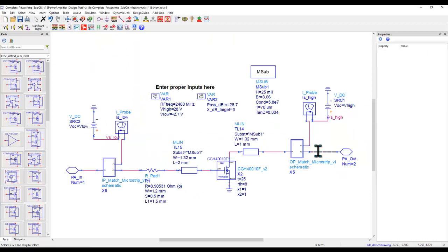So now everything has a footprint associated except this device because this is a power amplifier, remember, and high power devices we don't solder on the PCB but rather on the metal groove which we cut out from the PCB and we mount the device on our metal flange or the box in which we are going to assemble the amplifier. So I'm going to talk about that shortly.